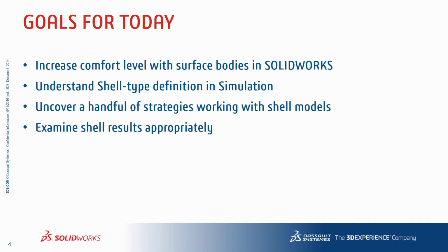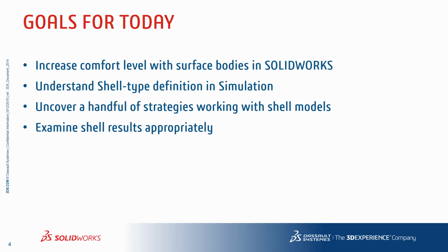The main thing I want to stress today is how important it is to be comfortable in SOLIDWORKS with surface modeling. And I'm not talking industrial design, swoopy shapes, modeling a mouse surface modeling. I'm talking about just the nitty-gritty core features of offset surface and mid-surface. So we're going to spend a lot of time in there talking about 5 different strategies to actually get to a shell element type. And then when we get to simulation, we're going to talk about how shells are defined and some of what the ramifications are for that.